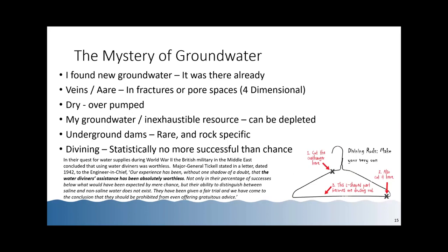When somebody says to us that their borehole is dry, it's very important to establish in what context that story comes about. Obviously, originally, it was worthwhile putting a pump down, so it went from being a production borehole to dry. Is it an environmental factor? Did somebody drill very close by to you? Or is your pump just too big? And that's often the case. The fact that people think that groundwater is inexhaustible or it's their resource is unfortunately not true.